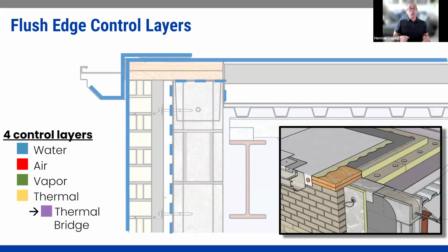So as we look at the water control layer, we're looking at basically three different things. We're looking at the main water control layer, which is the roof, the drainage system, and whatnot. But secondary to that is going to be the facade. That's going to push away the bulk of our water and really get us ready for management of the vapor as it comes through. You'll notice that the building envelope is now to the interior here, or to the outside of the inner wall cavity there.